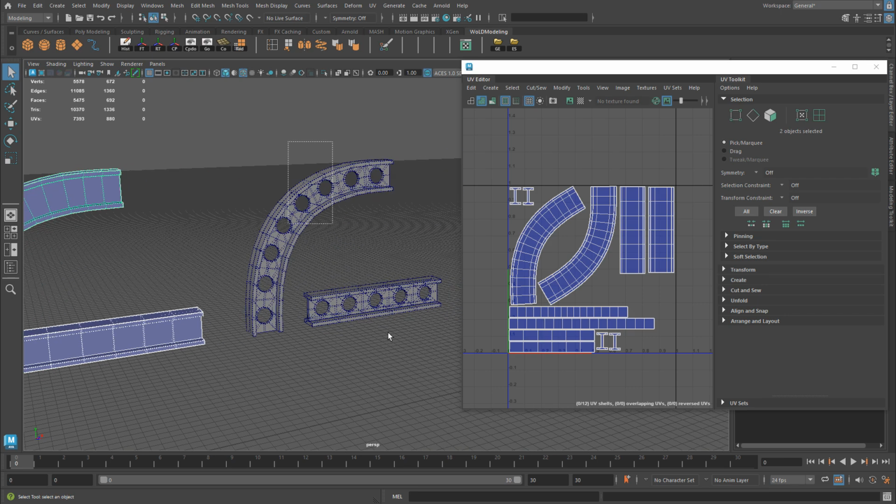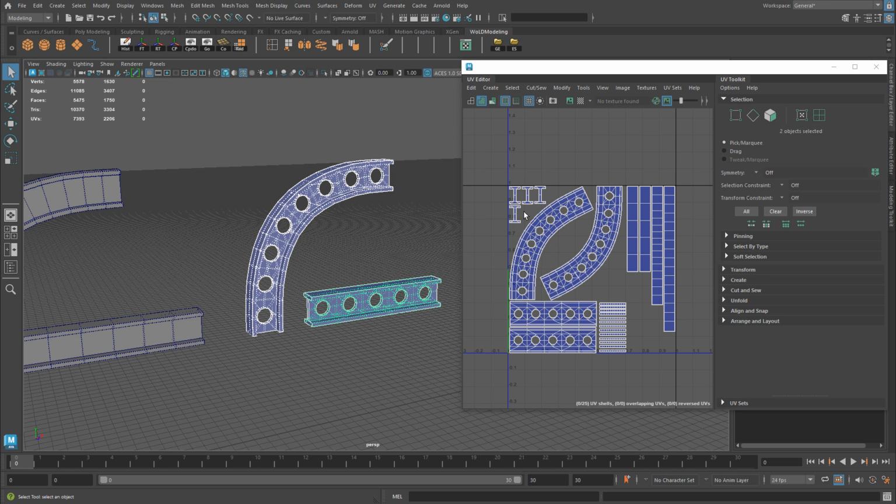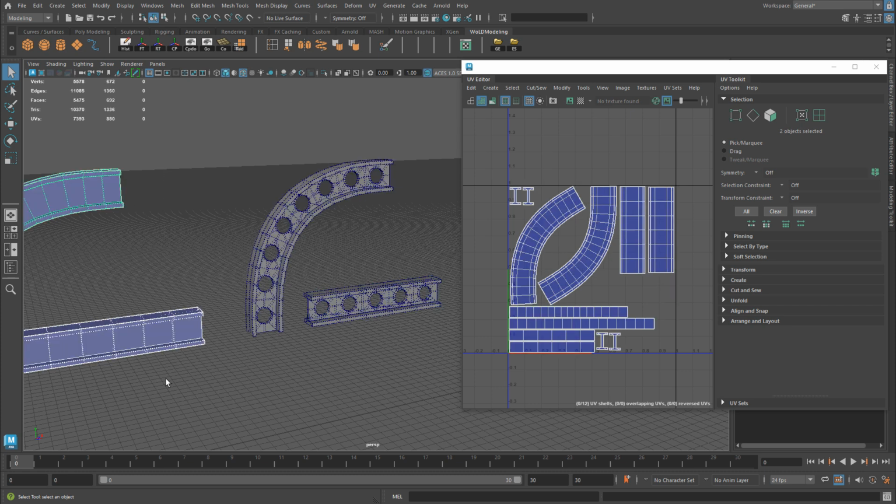And I did the same thing for these 2. I combined them into the same UV layout. They will receive the same texture, and for Substance Painter, I will export them both, so I can see them both when I texture them. And for all of these, no UV shells have been overlapped. They all have their own unique UV space. And again, this will help with mesh baking and to avoid those artifacts of elements not baking properly and just kind of causing artifacts from one part of the UV shell to another. So these are the UVs.